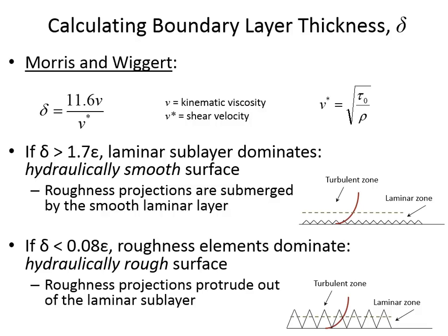right, and so if you're comparing the peak height rather than the flow conditions, if you had small roughness elements versus large roughness elements, then you're going to have more energy loss from the pipe that has larger roughness elements. And if you have more energy loss, the flow will be going slower, so you'll have a thicker laminar cushion. Just looking at this, it looks like the laminar on the top is bigger. Yeah.